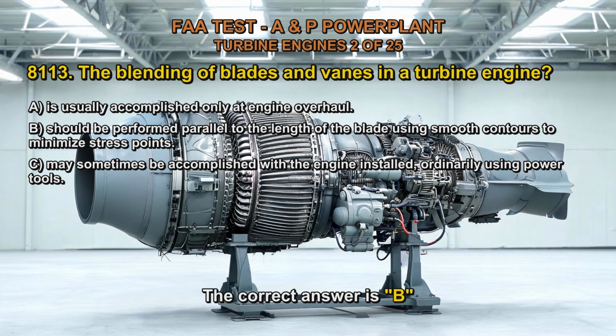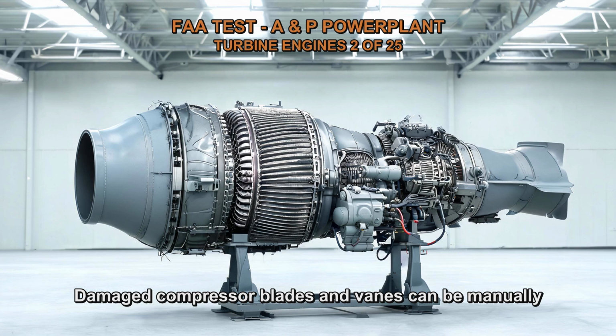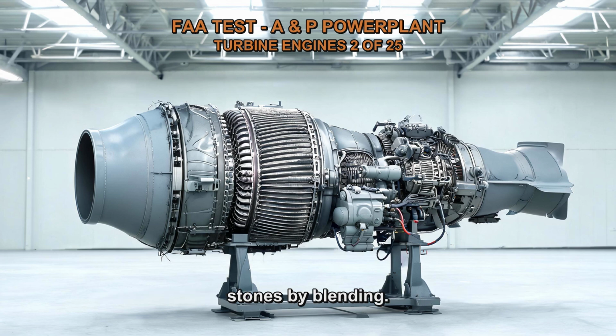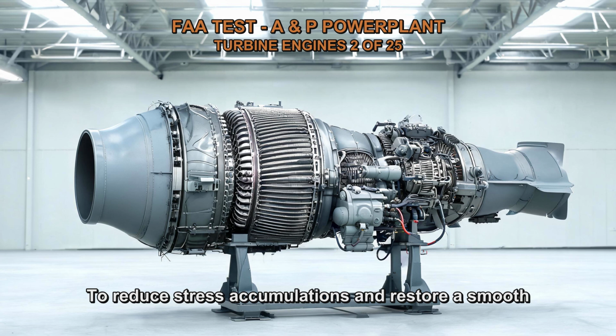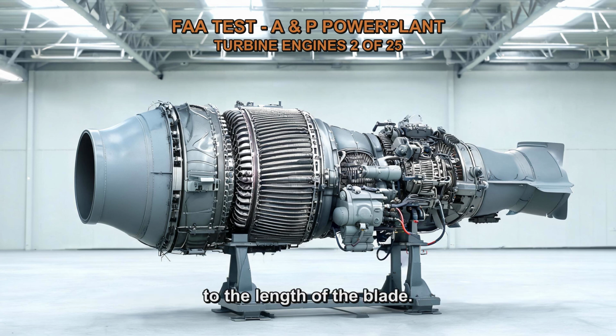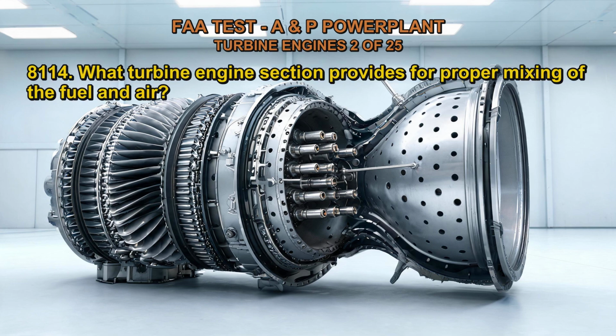The correct answer is B. Damaged compressor blades and vanes can be manually reshaped using small files, emery cloth, and honing stones by blending. To reduce stress accumulations and restore a smooth shape to the surface, blending is done parallel to the length of the blade.